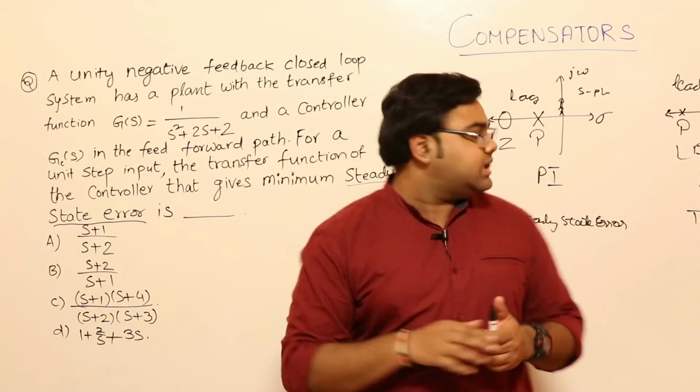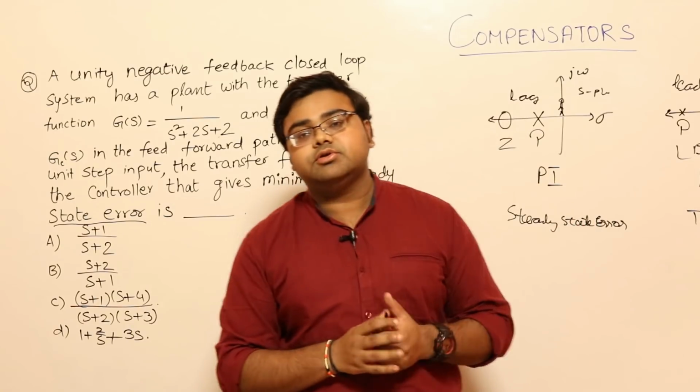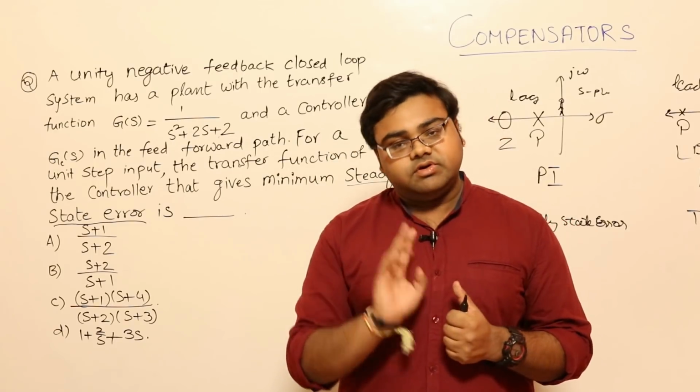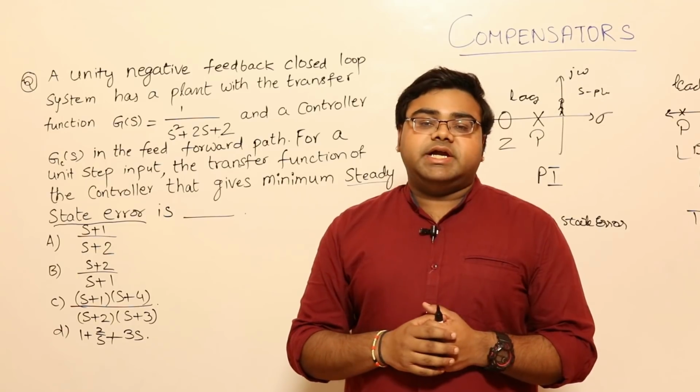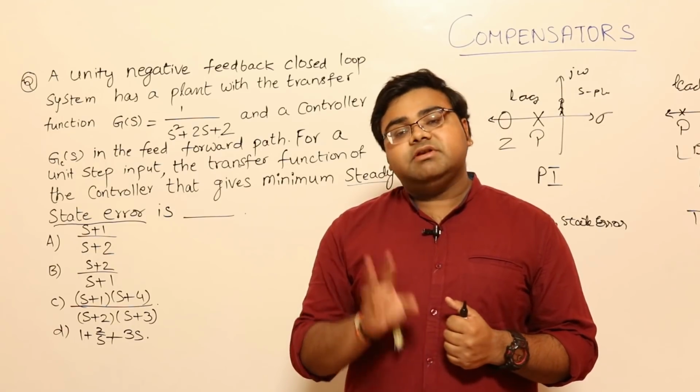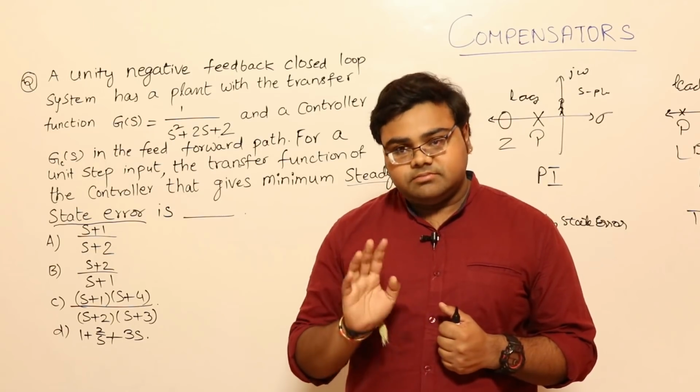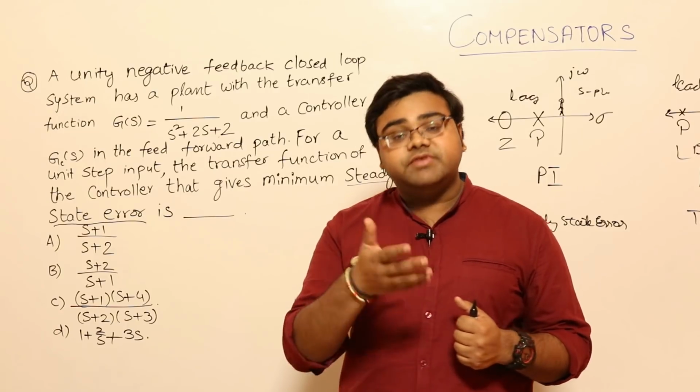What is that for steady state error? See the shortcut, a PI controller you should be in a position to use. Any one of these controllers you should use. Why not PID? I will tell you. PID will fix transient as well as steady state, but there should be something to fix in the transient.